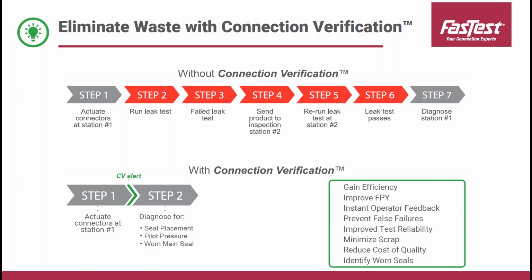With connection verification, you immediately know the connectors or the sealing devices aren't an issue. It'll give you immediate feedback as you're trying to actuate the connector, whether it's placed correctly, whether you have the right pilot pressure, or whether the main seal is good or not. So this leads to a gain in efficiency, an improvement of first pass yield, improved test reliability, and minimizing scrap in the medical world.